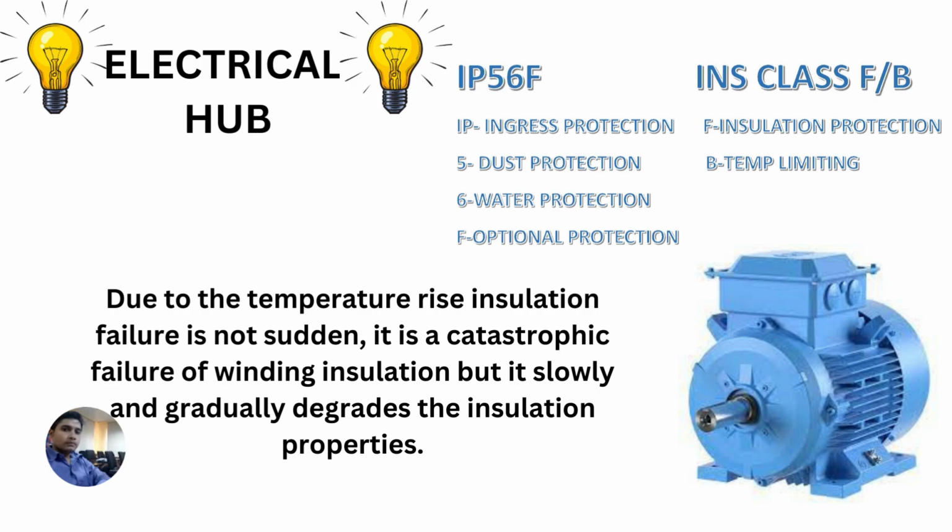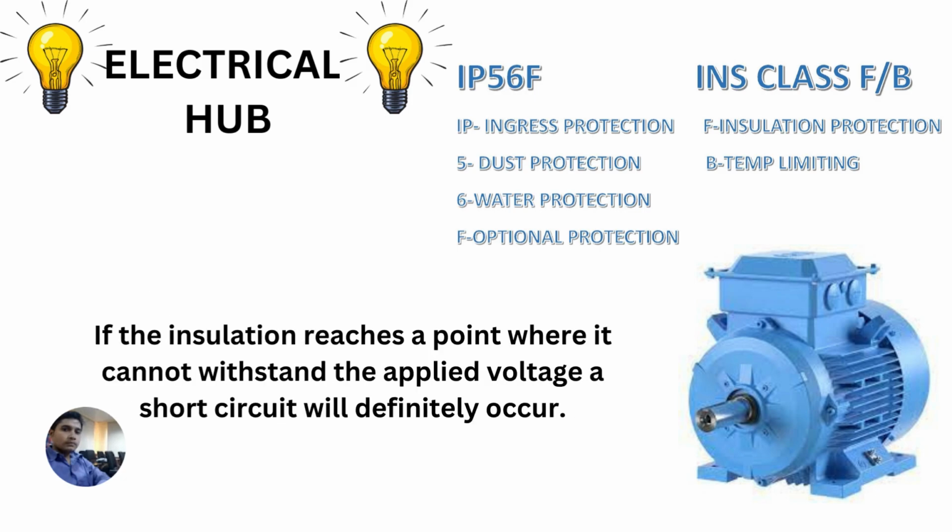It will reduce the life of the motor by half for every 10 degrees centigrade rise in temperature beyond the limitation.